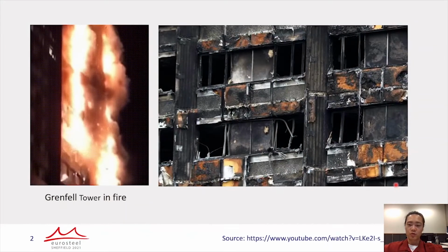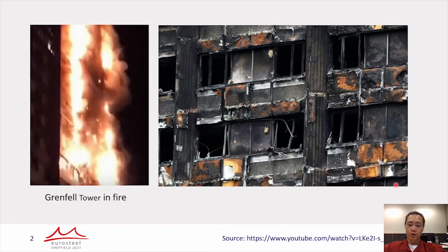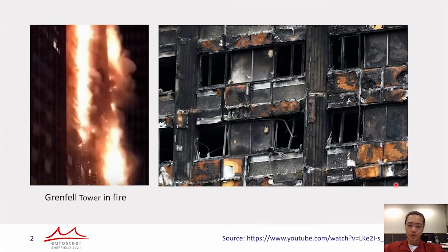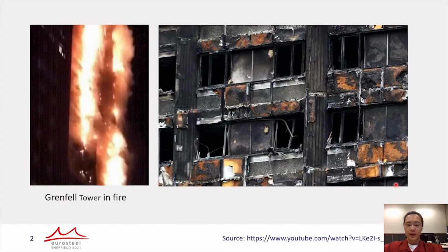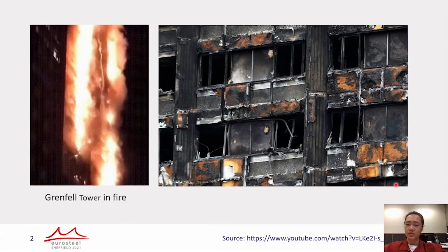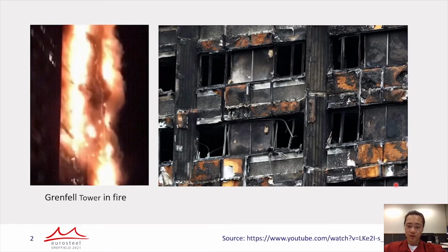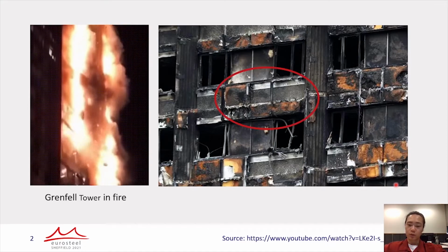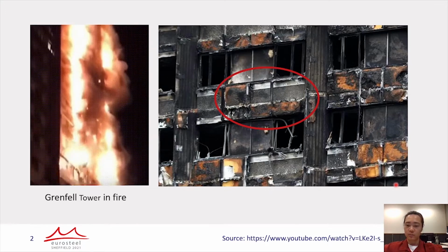The behavior of structure under fire is very complicated because fire introduces not only strength decreasing, but also thermal expansion, which causes additional load on the structure. And for building facades, the fire-induced collapse sometimes is not only due to the loss of the insulation resistance, but also due to the failure of other parts like glue layer melting, steel plate detachment, and critical component loss.